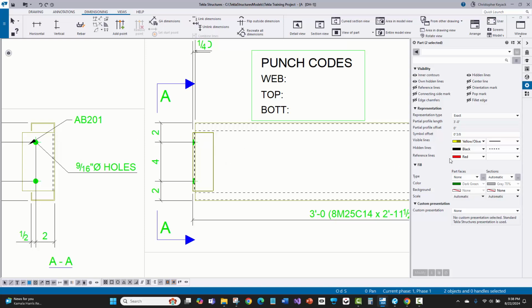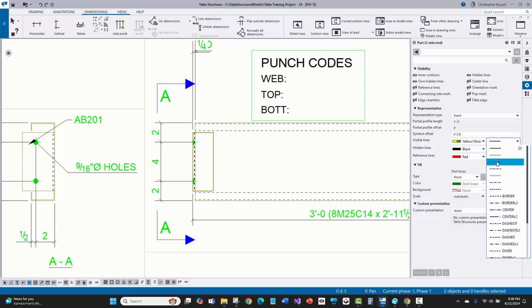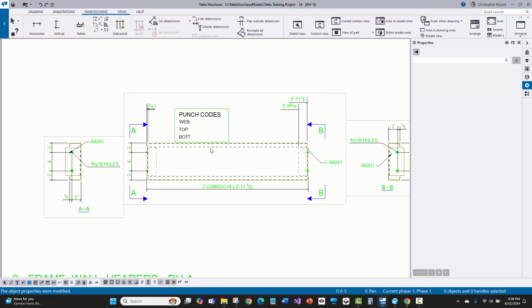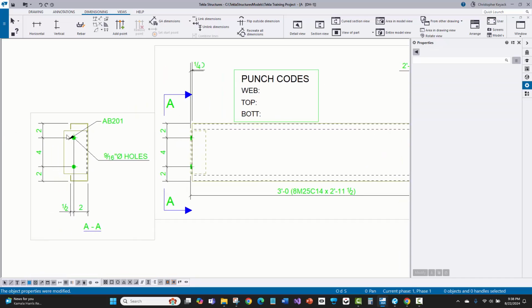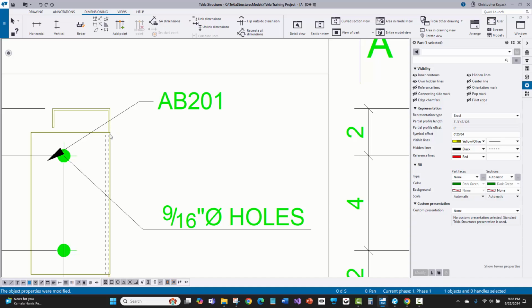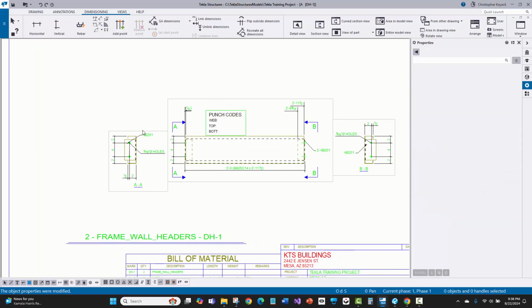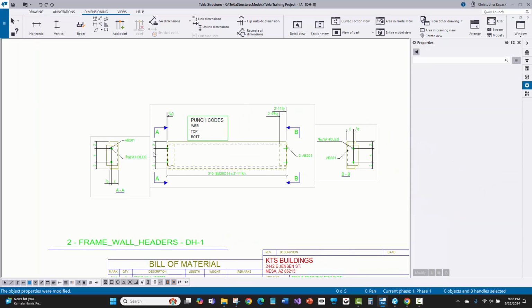And it's not being drawn as a hidden line, even though it is going kind of far side, like towed away. To quickly change that, I'll go over to the properties pane, switch this to hidden, and modify that. Then it looks a little bit more correct. Normally, if that was truly not centered on the material, where it's flush with a small clash there, if that was actually down farther, then that would be drawn far side automatically.